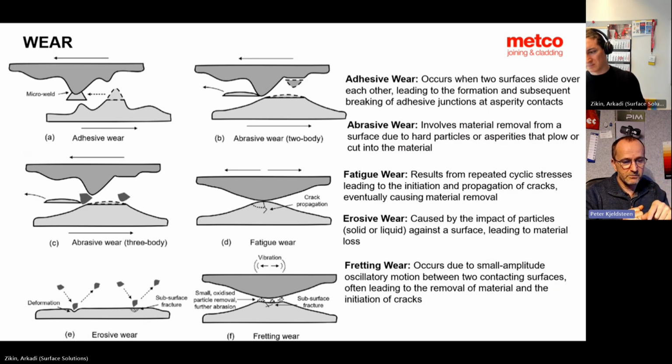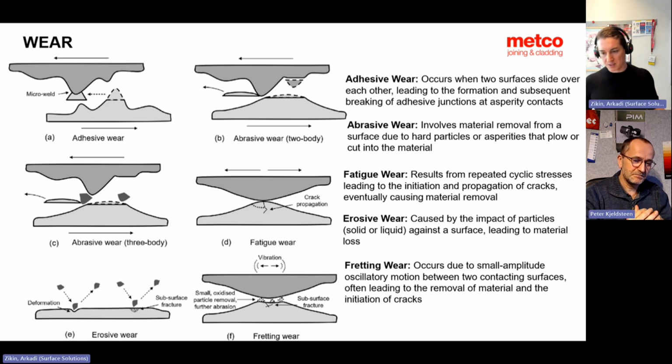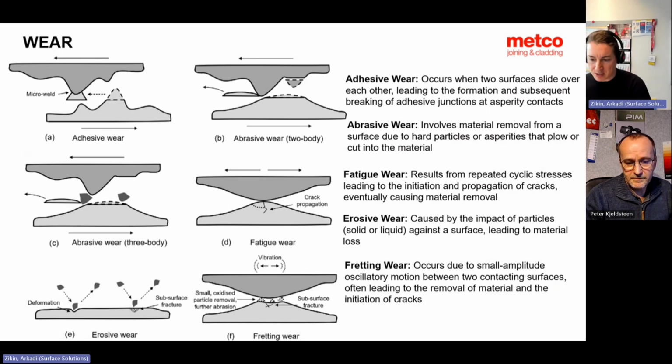So you will have these crack propagations going on maybe 2-3 centimeters below the surface. That's correct. But if instead of having a fully hardened material, you have a hardened surface and a ductile core, then if you can put this crack propagation zone in the ductile, you can avoid this crack propagation. That's true. That's sometimes pretty smart. It's even used as a method to stop crack propagation.